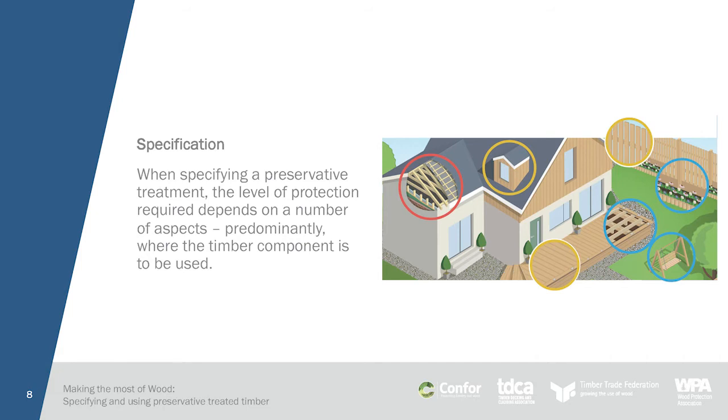Usually 15, 30 or 60 years. The national technical standards consider all of these elements and give guidance on the loading and penetration of timber preservative, all to ensure that treated timber is fit for its desired end use.